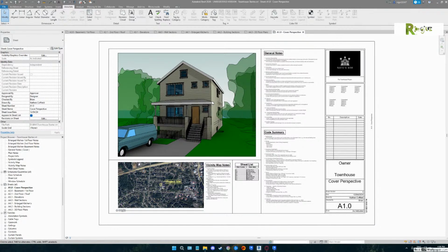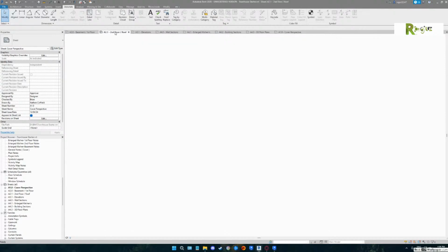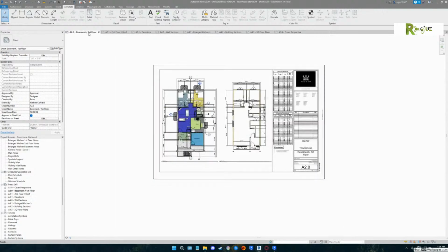It's looking good. You let me down with your asphalt shingles, so blow me away. Figure out how to put asphalt shingles up on that roof. Like I said, don't be surprised if you can't. That's why I asked the question. Make sure your trees are turned off anywhere they aren't necessary in any 2D views where we want dimensions, not fancy tree edges. Mostly in your sections. Definitely in your wall sections.